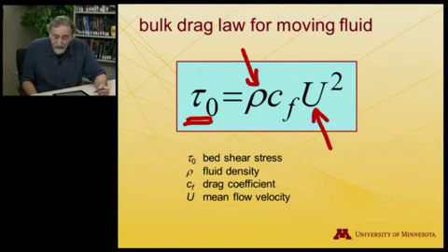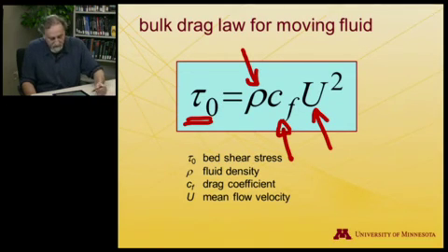And one bit of common experience you may have for that is that when you bike, for example, as you increase your speed, the drag on you increases faster than the speed does. In fact, it increases quadratically. So if you double your pedaling speed, you're going to have 4 times as much resistance to deal with. So that's why racing bikers try to streamline themselves and do what they can to reduce this drag coefficient over here. So that's the drag coefficient that we've defined. And at this point, it's just a number. We can tell that it's non-dimensional, but we don't know what its magnitude is.